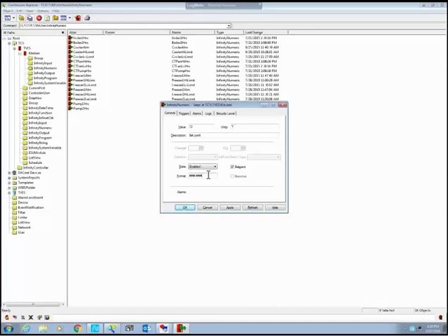And again, your format, if you want it to be 72.0 degrees, you need to format it with 4 pound signs and a period, then another pound sign to represent the tenths of a degree. If you wanted it to be 72.5 degrees, that's what you'd have to do.